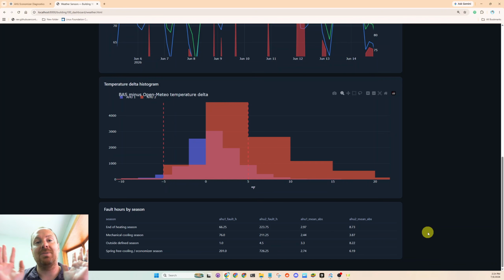So it happens all the time in the building automation system. The installers install it in a poor location. The electricians are always supposed to install the outside air temperature sensor in the shade on the north side of the building, and sometimes they have to cheat, and you can't get that wire stretched all the way from one end of the building to the other. It's just hard to do in some buildings.